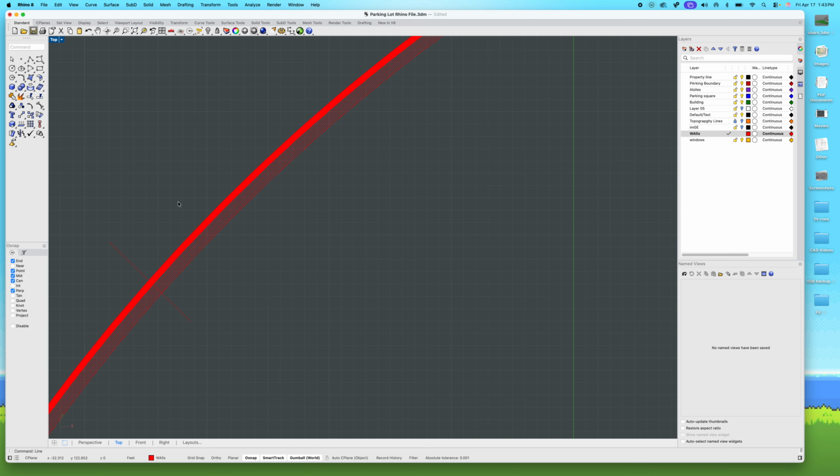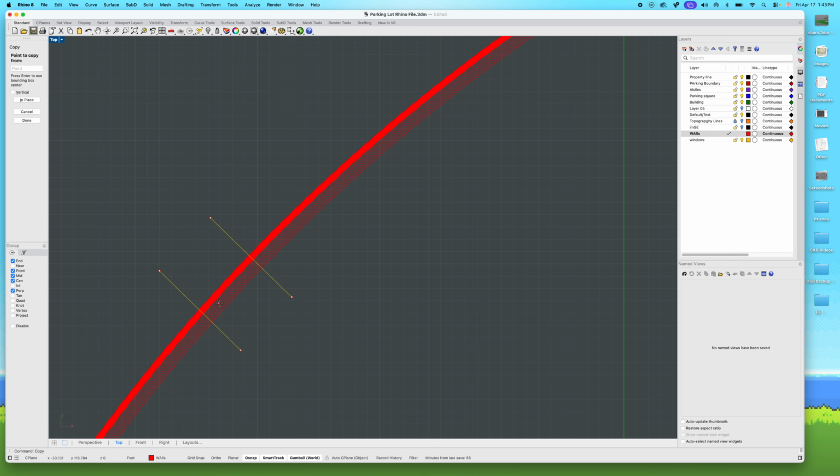Again, you'll see that I kind of just base it on, like, maybe it's a 6-foot window, so I'm going to offset 6 feet. Boop. And maybe we have a series of windows. I mean, why not? Copy. We've already got that distance in there. And maybe I kind of want a rhythm going on. That sounds cool. So I'm going to take those. Boop. I'm going to copy it because why would I do that over and over again?